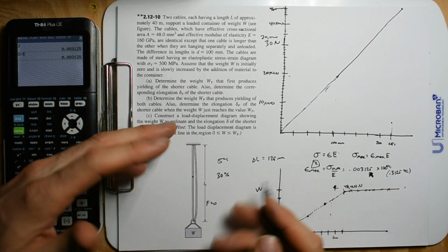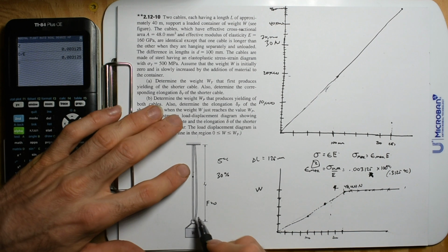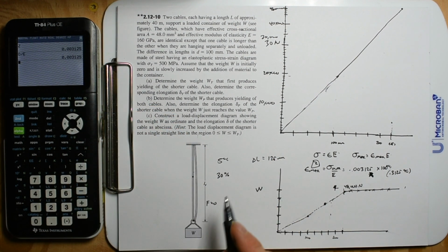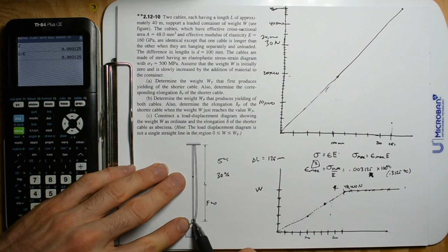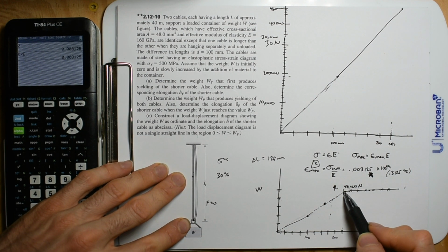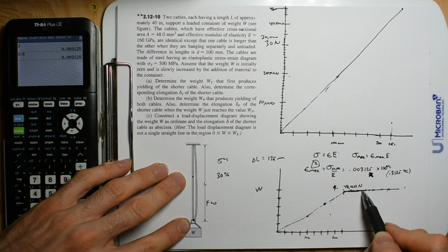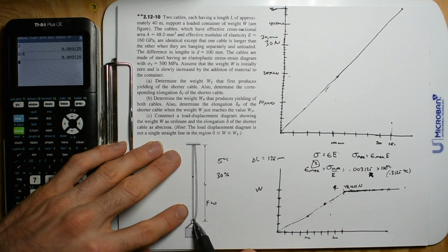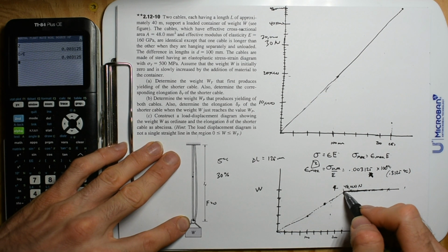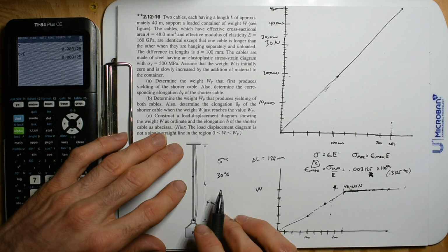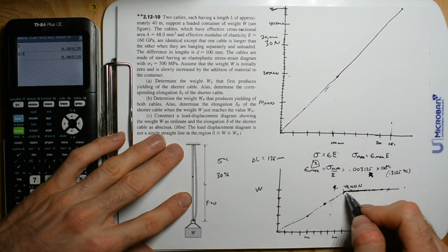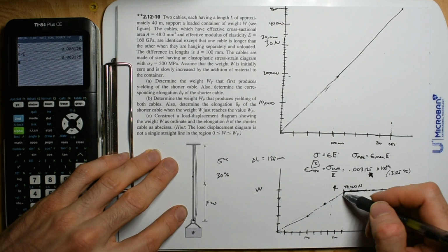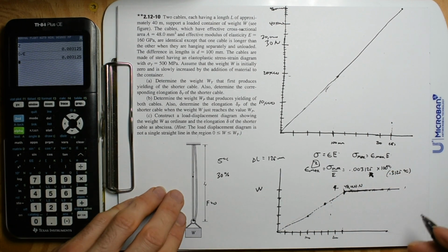But this is that classic case where it's just like, well, this is a determinate structure, and you have two cables to take the force, and it's going to be okay if one cable stretches. You know what I mean? Just because you get into a plastic range doesn't mean that you've permanently ruined the cable. You know what I mean? Some things are designed this way, but definitely not bridges and structures. Because, let's see, how can I word this?